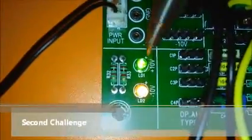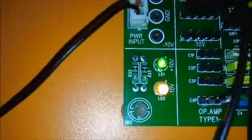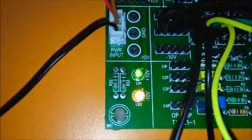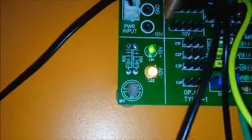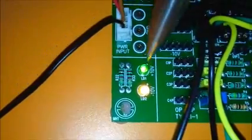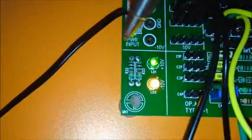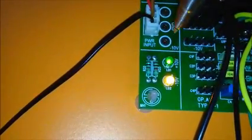The second challenge that we found was that these two LEDs, the plus 10 and minus 10 LEDs, are supposed to glow when a correct power supply of plus 10 and minus 10 volt is given to the board. He initially gave a supply of just 10 volt, that is a regulated power supply of 0 to 10 volt. Even then these two LEDs were found to glow. Because of that, the first time we conducted the experiment, readings did not match with the software simulation. But later, when plus 10 and minus 10 volt were given, the readings were found to be correct. So one of the main problems that we faced was that the LEDs glowed even when the proper power supply was not given to the board.